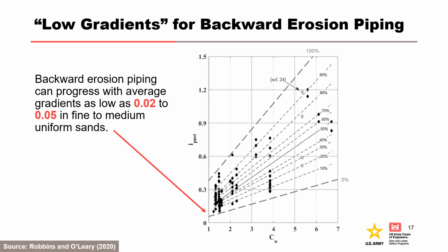Always specify hydraulic head difference over seepage path length, or H/L. Don't just provide the numerical value of gradient. This assists with quality control reviews and helps to clearly communicate seepage path length. Discuss key assumptions and parameters for estimation of critical gradients.